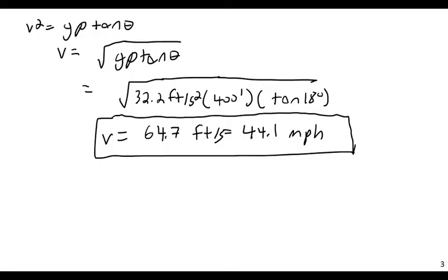You don't actually get more for adding more weight, because if you make your car heavier, yes, the frictional force increases, but in turn, the amount of frictional force you need to accelerate, stop, or turn will go up in proportion. So you don't actually get anything out of having a heavier car in terms of friction, at least in terms of very simple turning radiuses. There can be other benefits for snow and things like that, but that's something different.